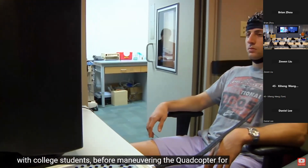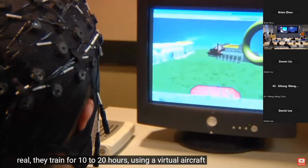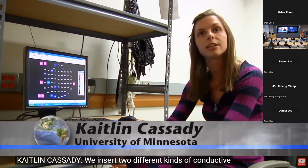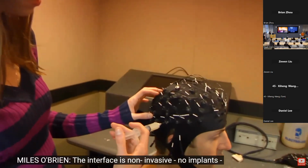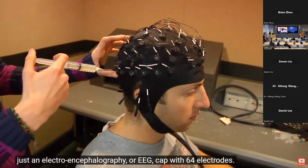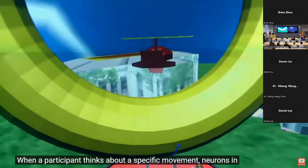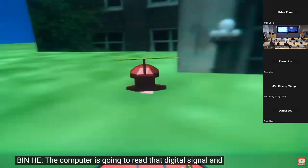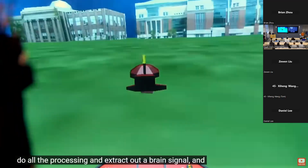Before maneuvering the quadcopter for real, they train for 10 to 20 hours using a virtual aircraft flying over a computer-generated campus. We insert 2 different kinds of conductive gel that help us conduct a signal from his brain. The interface is non-invasive, no implants, just an electroencephalography or EEG cap with 64 electrodes. When a participant thinks about a specific movement, neurons in the brain's motor cortex produce tiny electrical signals. And the computer is going to read that digital signal, do all the processing, extract out the brain signal and control the quadcopter.